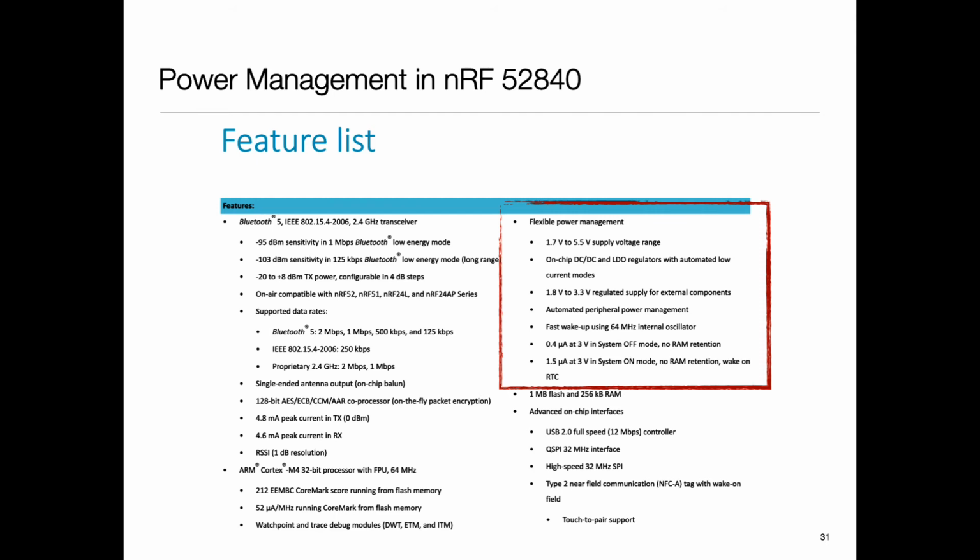Because power became such a dominant concern, all across the hardware software stack things ended up getting optimized. So that's why, if the time to put it to sleep and wake up is too long, or the time to change voltage or frequency settings is too long, then a lot of these benefits get totally negated. So that's the underlying story.